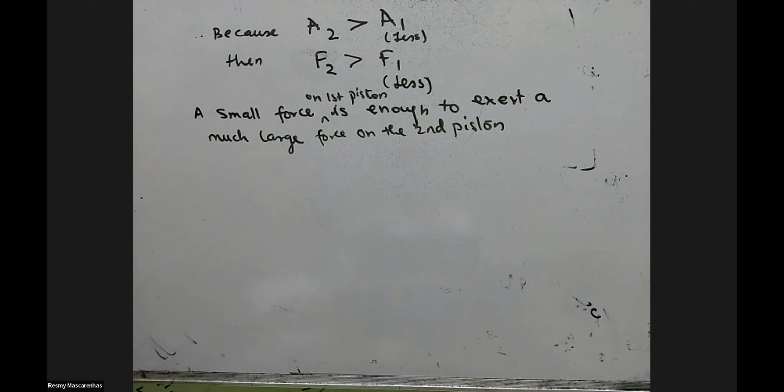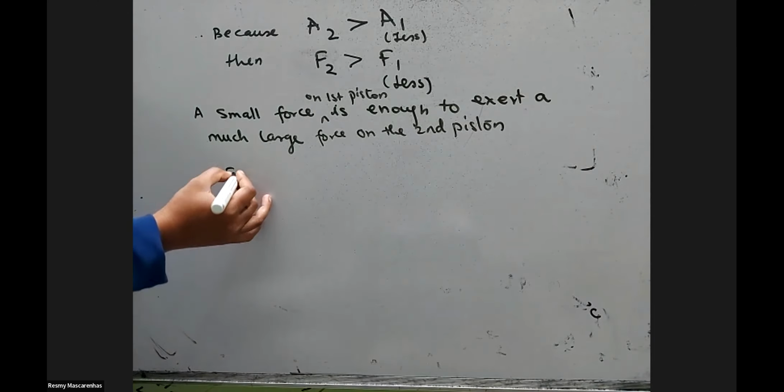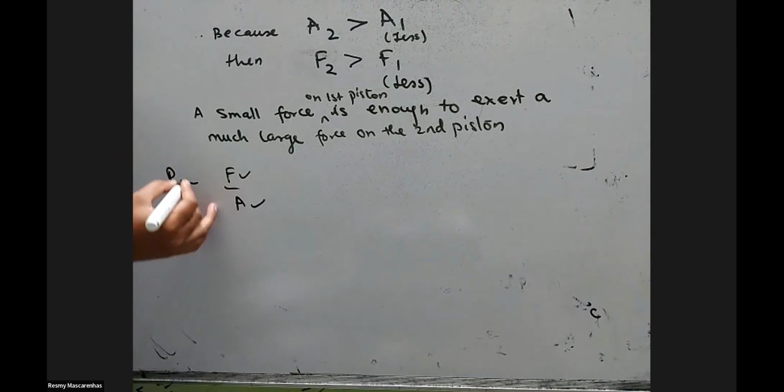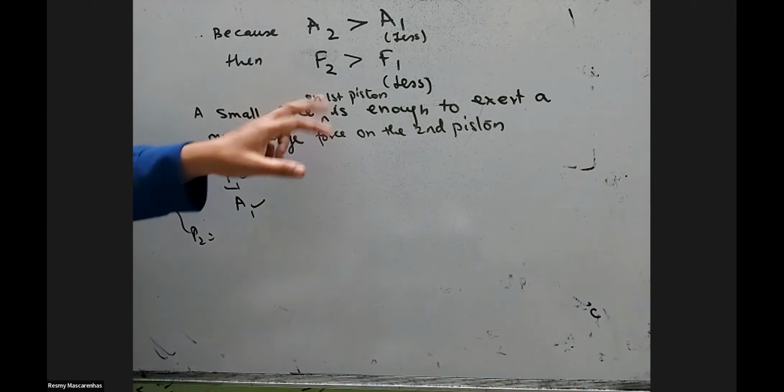Pascal doesn't say force is the same at both sides. Pressure is the same. Force and area will change accordingly. P1, P2 will remain the same. Only F1, A1 will change accordingly like this.